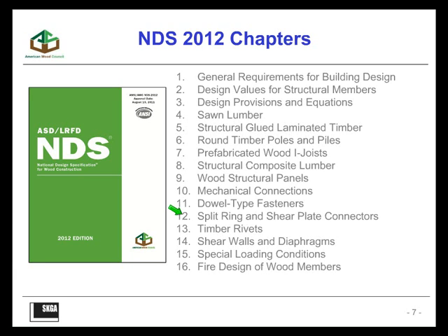However, I think the most significant revisions in terms of impact on your designs probably happen in Chapter 11 in the fastener section, Chapter 13, Timber Rivets, Chapter 3 on bracing, and also Chapter 2 if you're doing LRFD design for compression perpendicular to grain. And based on the poll results, I'm not sure that's going to be of much interest to folks, so I'll move through that part quickly.